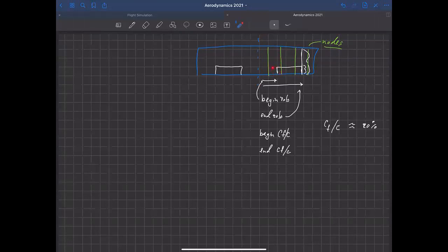This aileron could extend a little bit further out over here and not change anything about the way that we're modeling this. Of course, we're looking at this first with very few sections along the wing, but eventually we crank this up to like 50 or 100 sections along the wing to get more accurate results. That allows us to more accurately capture where the aileron begins and ends. That's one of the many things that having more nodes along the wing allows us to do.